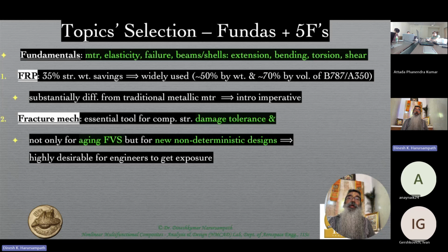For example, if you say Young's modulus, you give a particular value for a given material. In the same lot, if you make two different samples and test them using a uniaxial testing machine, called a UTM, you apply an axial stress and use strain gauges to read the strains, and then you plot both of them. You get the stress-strain curve and the slope is the Young's modulus. You would see that for one specimen, it's slightly different from the other specimen, even though both were made from the same lot, bought from the same manufacturer at the same time.